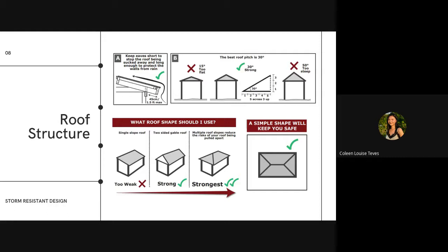And B is that the roof slope should be at least 30 degrees, and it would be redirecting the wind upwards rather than over the structure, but not too steep like 50 degrees, which would tip the roof instead, as it is enough for the wind to push a flat surface rather than rolling it over like the 30 degrees roof. The roof shape, also the strongest to counter the wind, is the hip roof, since it has more slopes for the wind to be redirected rather than your roof being pulled apart in a one-sided manner.